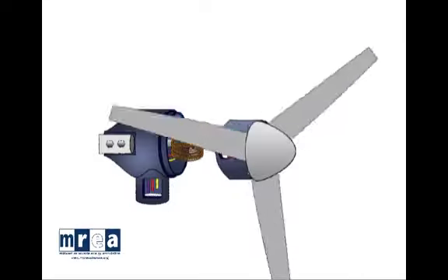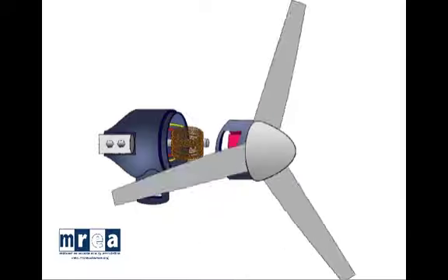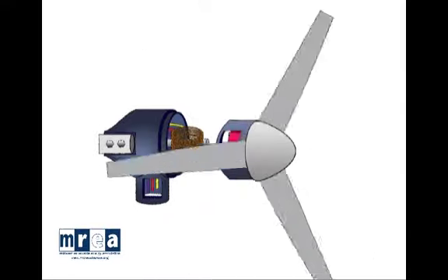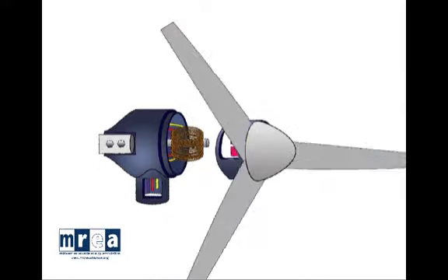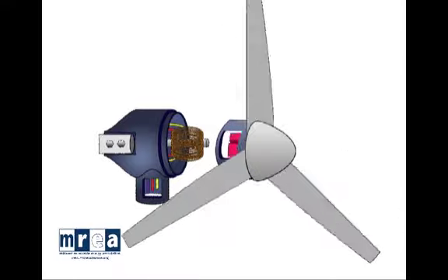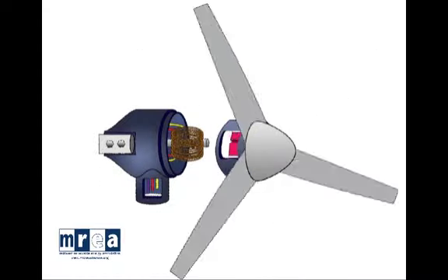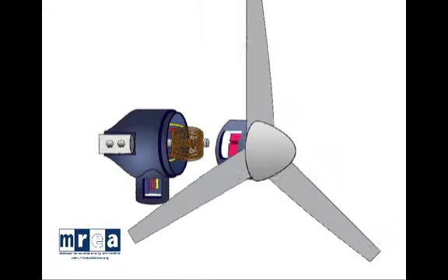In this animation, we're going to take a closer look at what happens when the rotor or blades rotate with the wind. Here we see that the wind must be blowing as the rotor is spinning in rotational motion. Beyond the blades, we can see that the magnets with the generator are also spinning with the blades. In the alternator, we can see a looping of copper wire that remains stationary attached to 3 conduits coming down from the base of the alternator.